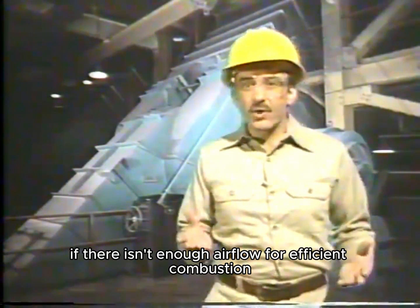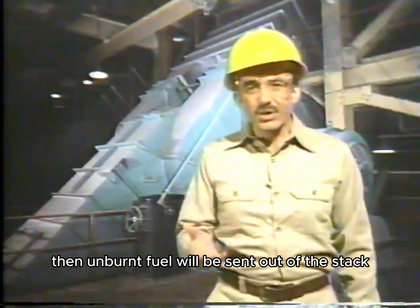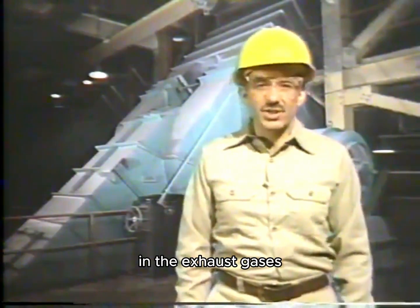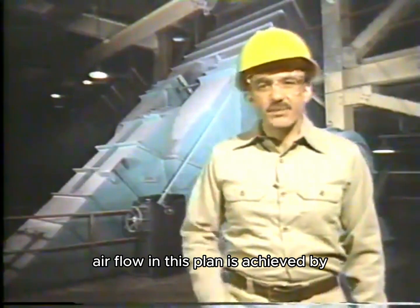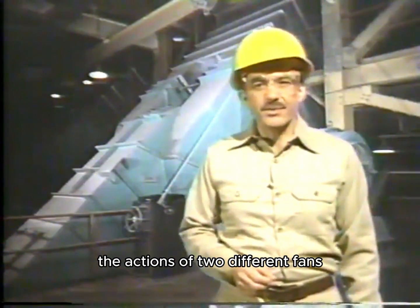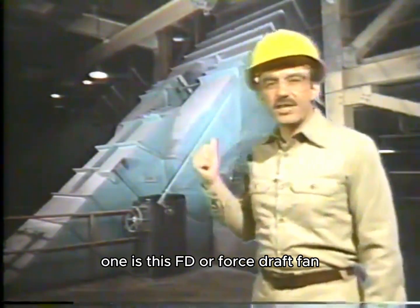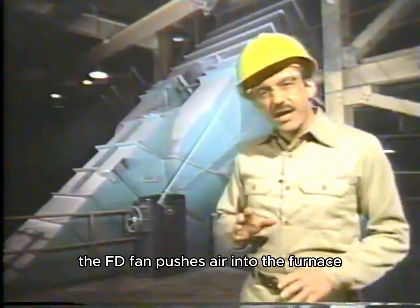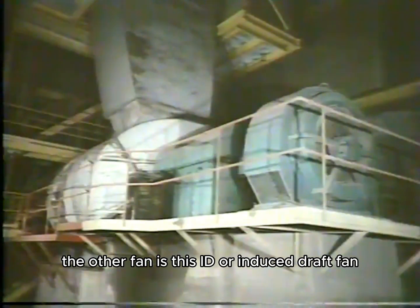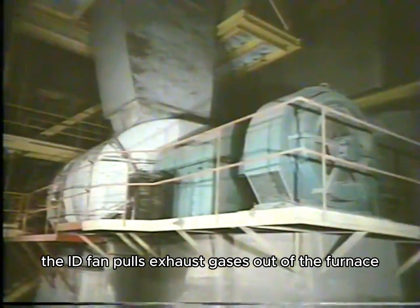If there isn't enough airflow for efficient combustion, then unburnt fuel will be sent out of the stack in the exhaust gases. Airflow in this plant is achieved by the actions of two different fans. One is this FD, or forced draft fan. The FD fan pushes air into the furnace. The other fan is this ID, or induced draft fan. The ID fan pulls exhaust gases out of the furnace.